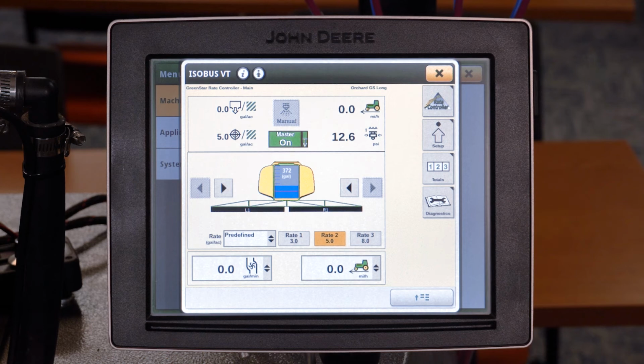Third, if the pump is running but doesn't appear that any product is moving, you may have to remove a hose after it leaves the pump, but before it reaches other restrictions, to see if the pump is moving any liquid. So if there is an error message, what is it? What does it say? When does it come on? That will give you some clues as to where to look.